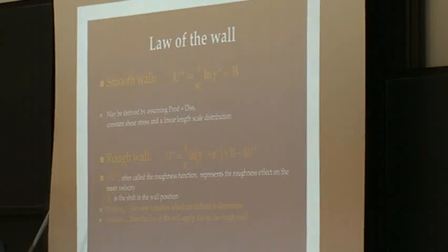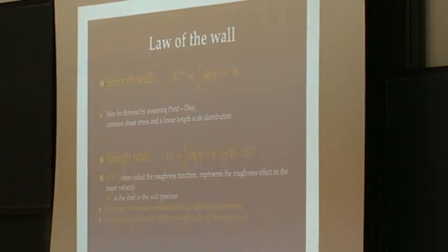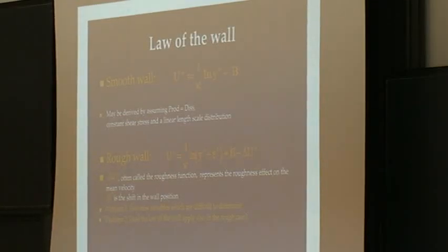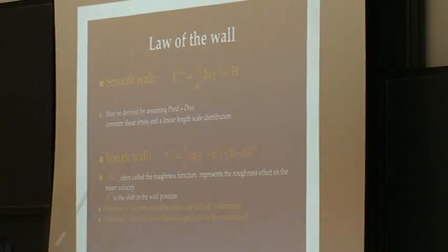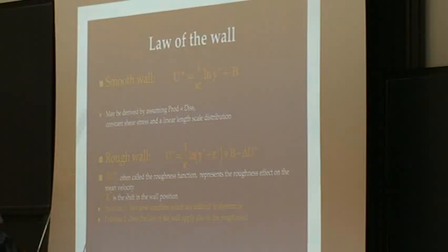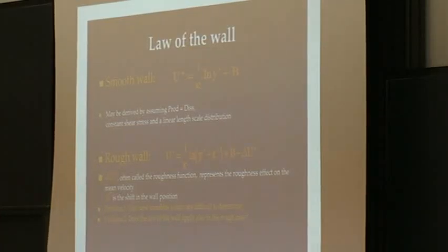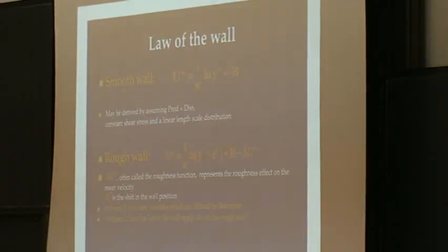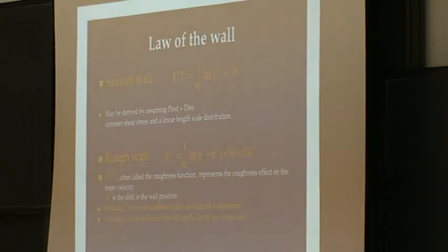So, if we want to scale our measurement in such a way, we have added two new variables. And since it's not so easy to measure the wall shear in the rough case as it is in the smooth case, although it's difficult in the smooth case as well, we can't use established techniques from smooth walls like the oil technique that we saw in the previous session.